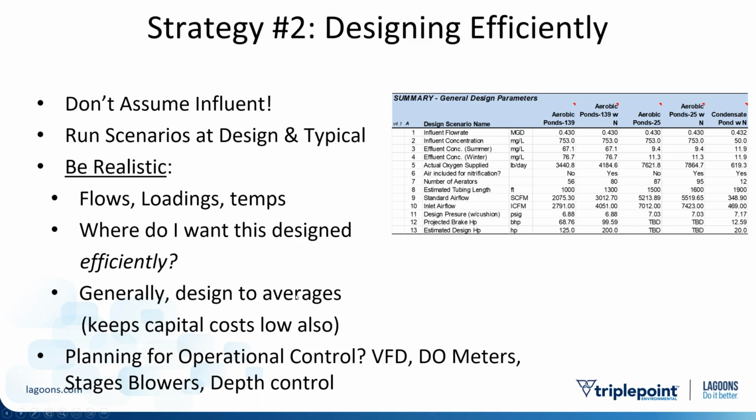Also, as you're designing wastewater treatment systems, it's important to give the operator some levers of control. So getting them a handheld DO meter, getting them VFDs, considering staging the blowers such that at design condition we use 2 blowers, but on average conditions, we only have to turn 1 on. And then providing some mechanism for depth control if the lagoon process allows for it is helpful as well.